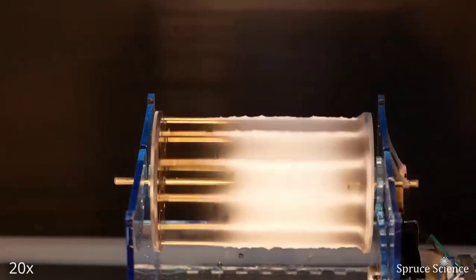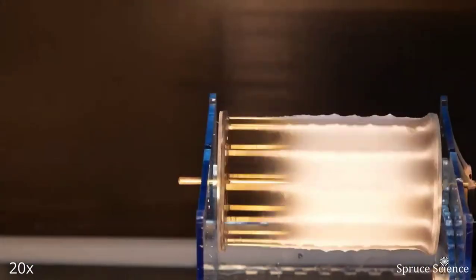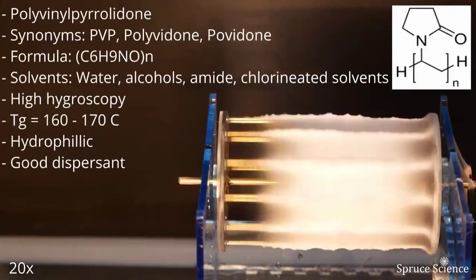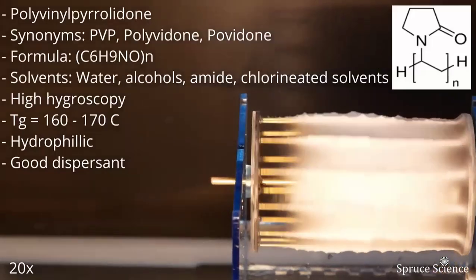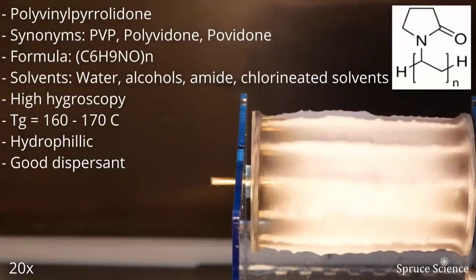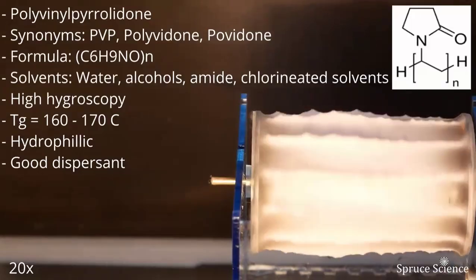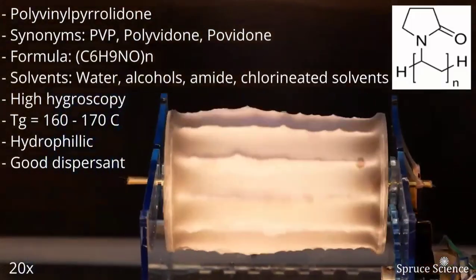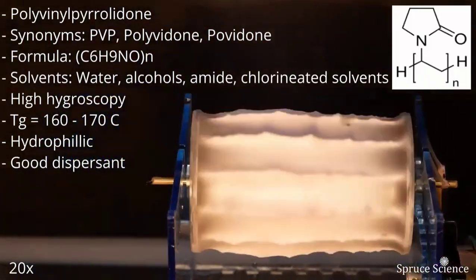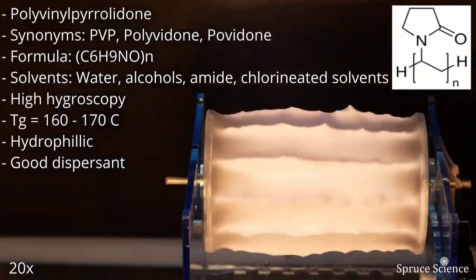We are briefly going to talk about the many benefits of using PVP in your electrospinning process. PVP is a synthetic polymer that is soluble in water and alcohols, making it easy to work with and form into films. It attracts and holds on to water molecules from the surrounding environment and has good wetting properties. PVP is a versatile material with high heat resistance and good adhesive properties.